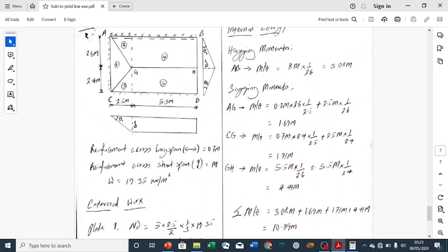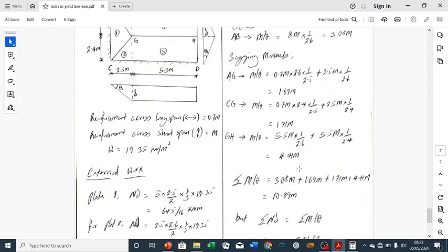We now calculate the one due to plate 5. The length of the yield line is still 5.5. The moment is still M because it's still resisted by vertical reinforcement. But theta, if you look at this distance, is 2.4. So theta is 1 over 2.4. So when we calculate that, we have 4.41 M. I will go ahead to calculate the sum of internal energy.